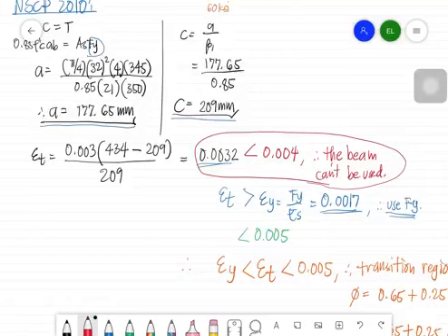It might be brittle later. In order for it to be safe in all aspects, we should meet the ductility requirement as well, aside from meeting the given Mu of the problem. I think that's all for problem A and problem B. So stay tuned, guys, for more examples.